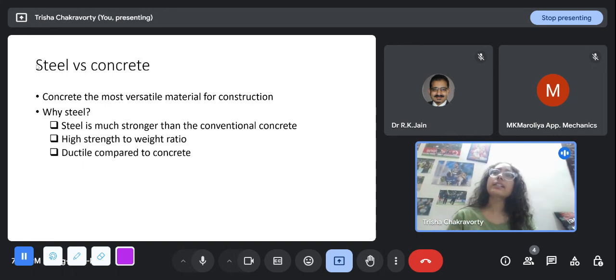That is how we define ductility, and we need ductility in design, because if material undergoes ductile failure, it will undergo a lot of strain. And even though the stress capacity may not increase a lot, as it deforms a lot, it will give sufficient warning time for people to evacuate, and we want ductile failure compared to brittle failure. Brittle failure occurs very suddenly and it can lead to loss of life.